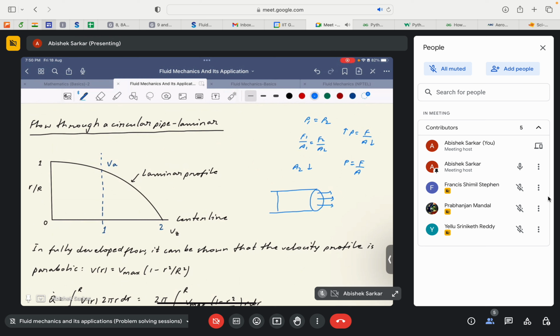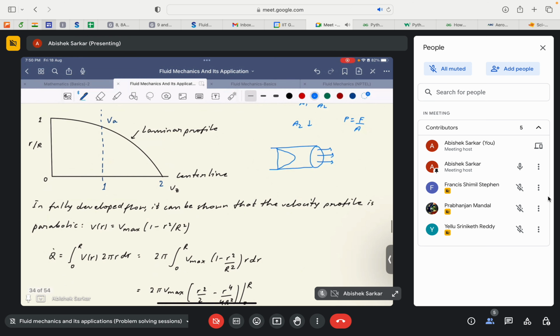and we are being told that the flow follows a parabolic velocity profile. Okay, and if this denotes Vmax, the maximum velocity, that is inherently understood to be reached at the middle or central cross section of the pipe, because this is the point which is farthest away from the wall.